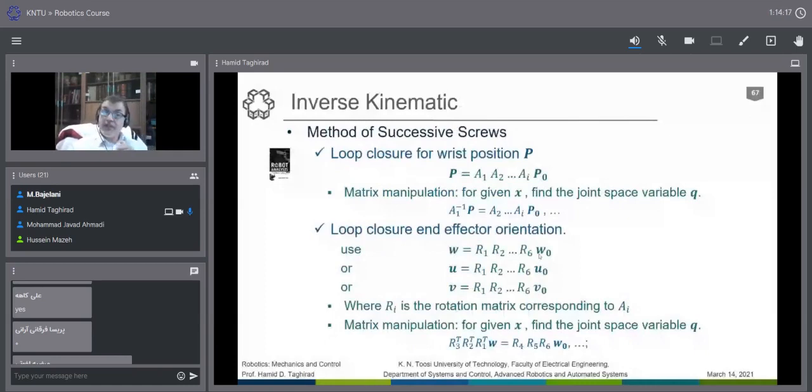But if not, this problem becomes much more difficult. We have 4 parameters over there, but only 2 parameters remaining in this part. We have a more difficult time solving the positioning part of the inverse kinematic, but a much simpler time with the orientation part.